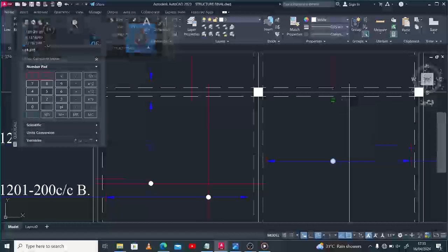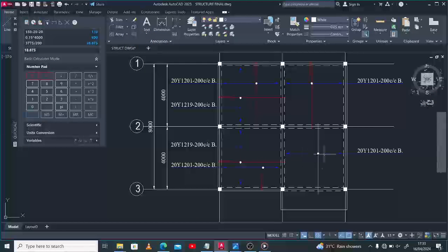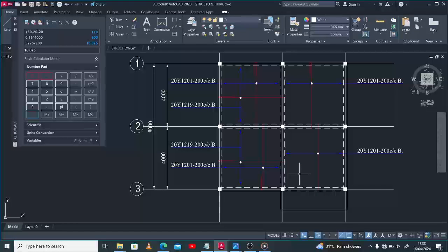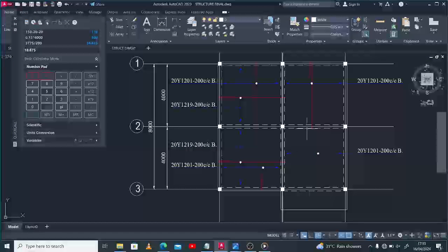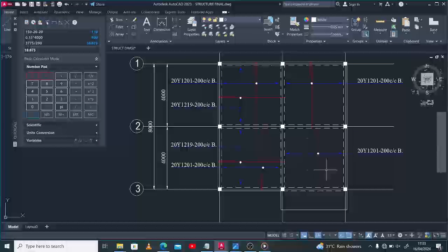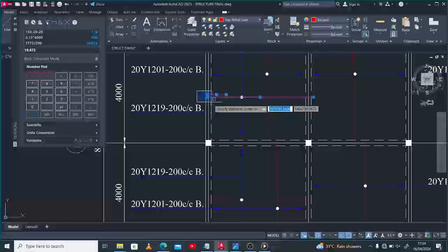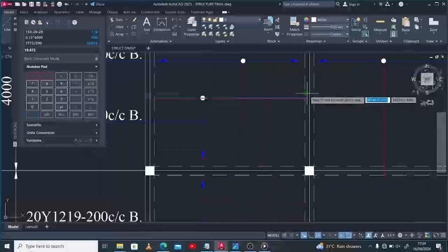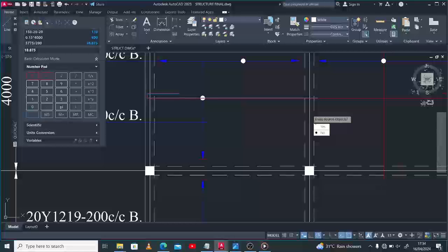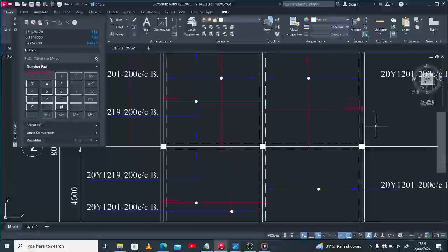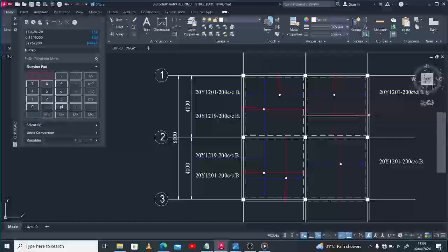All right, so that's how it works. So to change this, let's just match it. Pardon me. So that is how we've sorted out the bottom reinforcement on this side. Then to have the other horizontal reinforcement for the panels on the right, what we'll do is to have the same thing done on the left but on the other side. Since it's the same reinforcement type and the same span, you might just come and mirror what you have here on the other side. All right, that's one of the ways to work smarter, instead of coming to draw and return again.